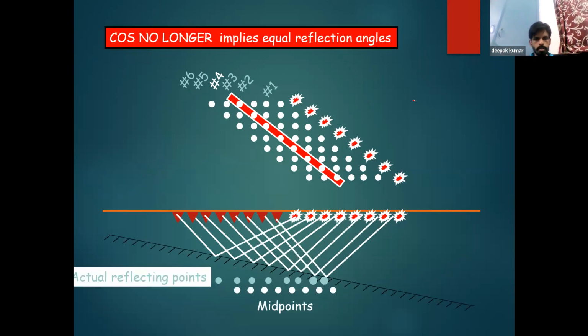See, again, I talked about how we will apply the migration for a dipping layer. Okay, so what happens? The actual midpoint for any shot point is this, but the rays hit the surface here. So for that scenario, the data gives us the perception that the depth of investigation is different than the actual depth. So in that scenario, we'll have to apply migration. Okay, depth migration.